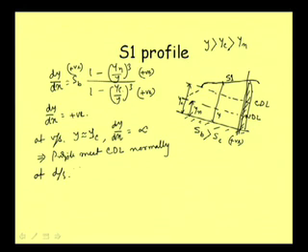what will happen is that the depth will be y equal to y control. So, this is a subcritical flow, and although it is on a steep slope, do not take it that if the flow is on a steep slope, it is always supercritical. It is not like that. Only if it is flowing as normal uniform flow will it be supercritical.